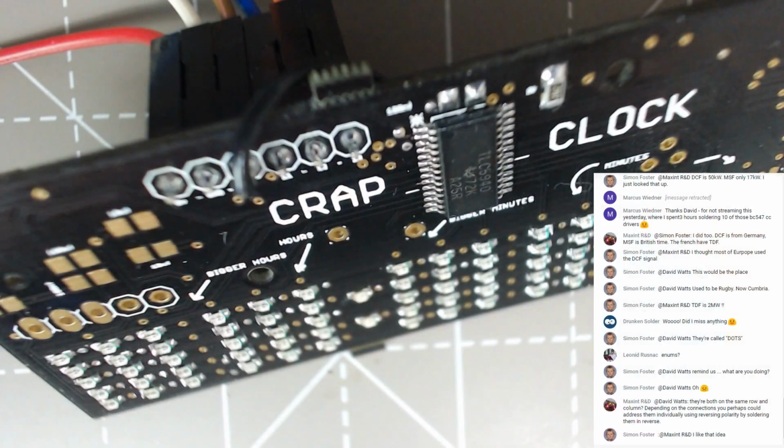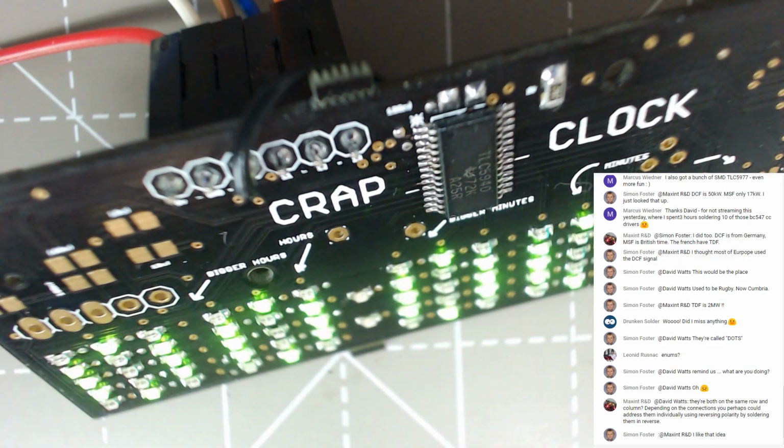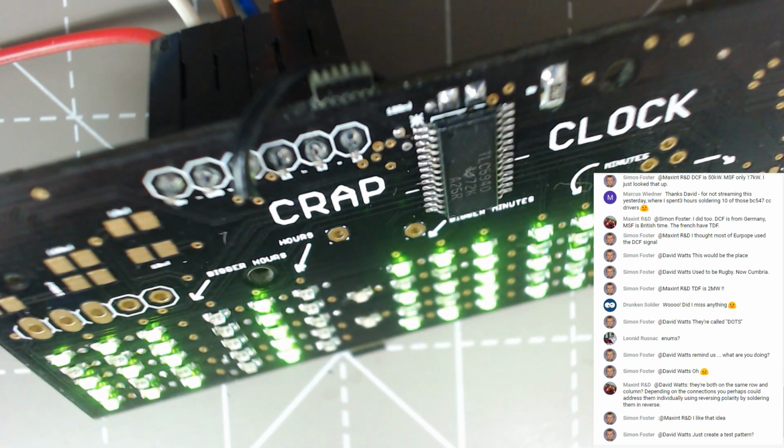I don't want to need to stop pressing that button. I don't want to make life difficult for myself with reversing the polarity. Plus you can't actually sink current in the other direction, because the TLC5940 can't source current. It can only sink it.